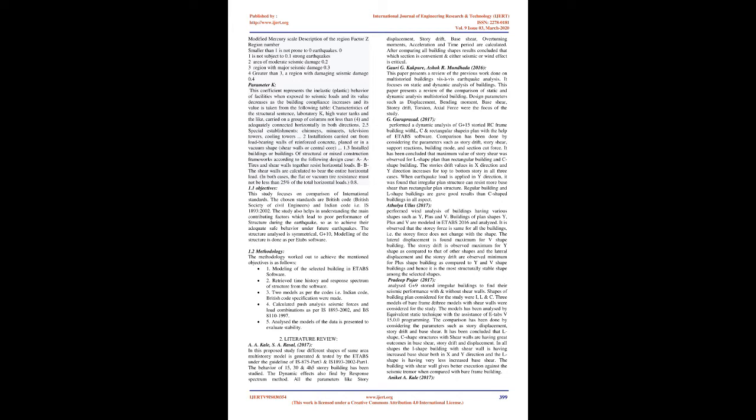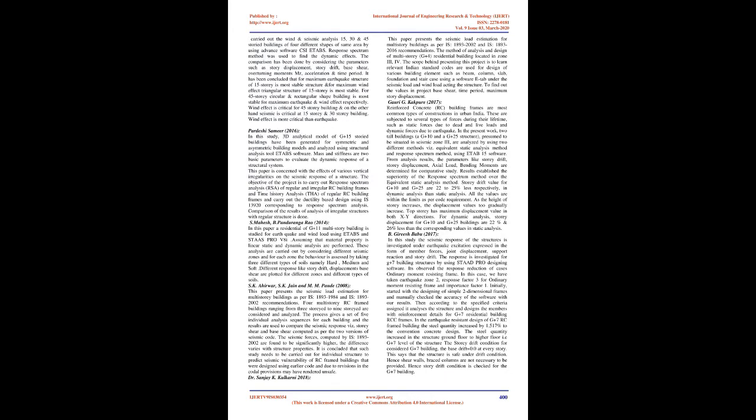This method relies on converting the seismic dynamic forces into equivalent horizontal static forces that affect the building in a horizontal direction, according to the main axis of the building. This method is used in the case of small structures or almost regular shapes with a section that is fixed or semi-fixed along its entire height, and where the setback in the horizontal projection does not exceed 25% of its area on the upper floors.